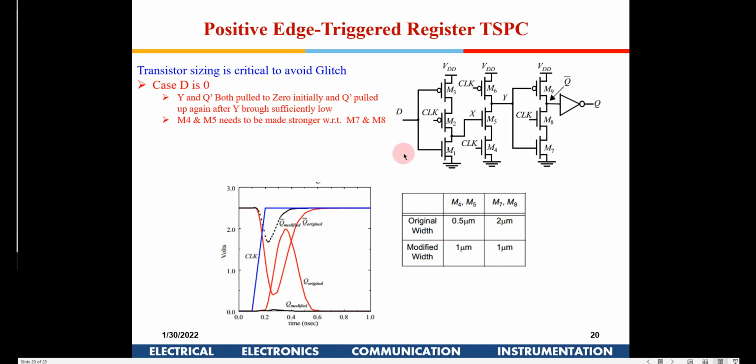Okay, there is another issue out here, but it has got other advantages, right? We are talking about a single clock, without clock and clock bar, and it is jitter free, so jitter resistant. So you can see the advantages are very many, because in these circuits we are using a single clock, so all those jitter issues are not here. So this small little bit of one additional gate delay is not much compared to the other issues.